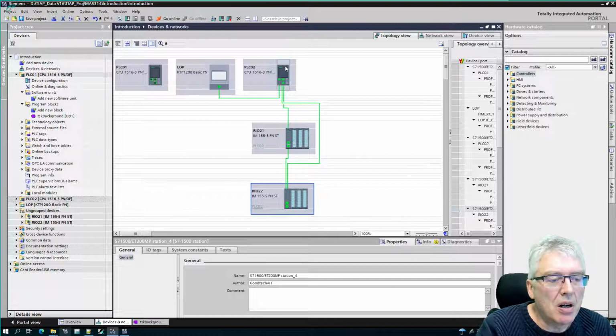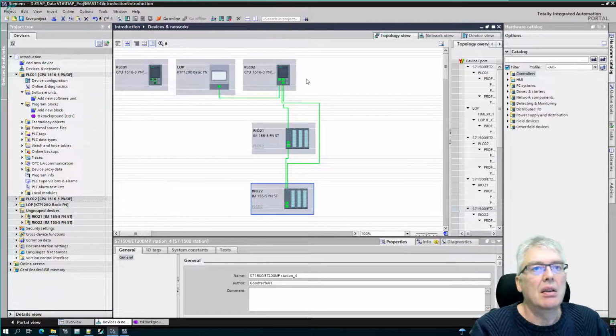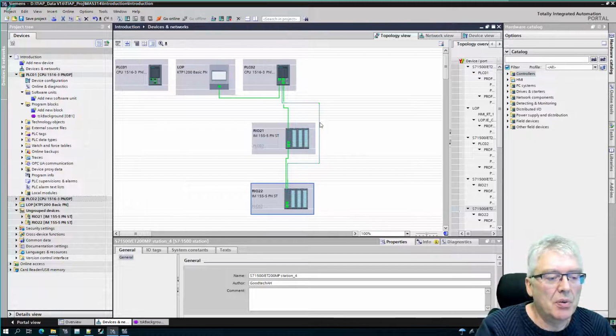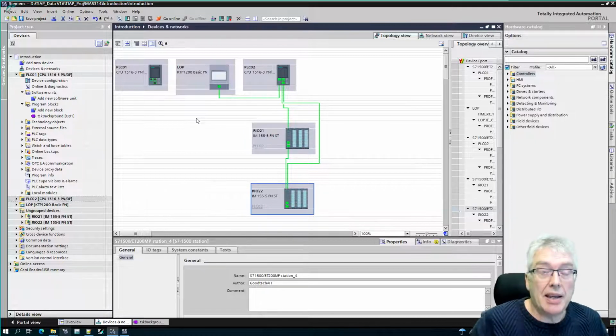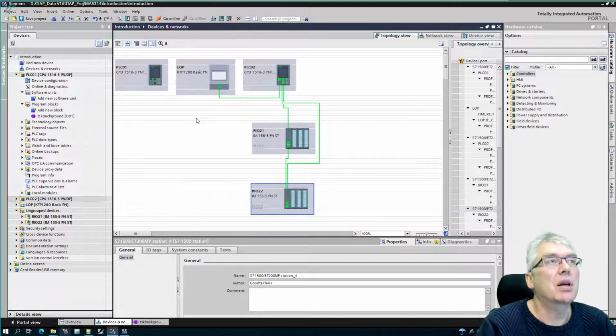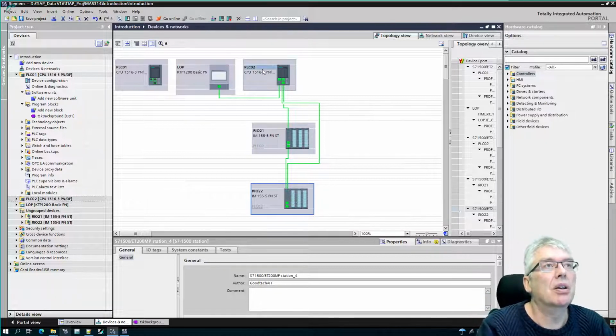This is what we call hardware redundancy. This network is connected in a ring. So if you have a breakage here, your system is intact, because then it communicates down here. If it breaks here, it communicates down here and back. So this is hardware redundancy in communication. So that's the physical topology.